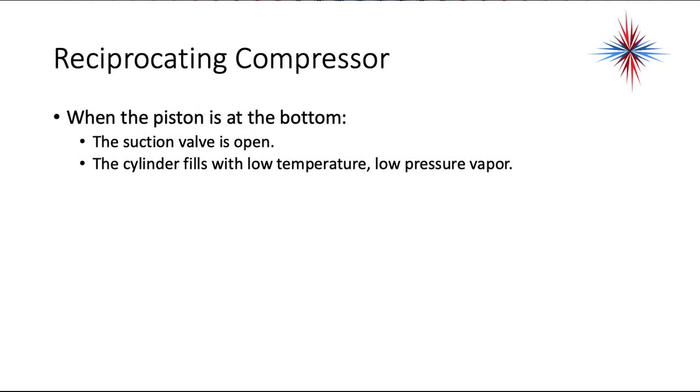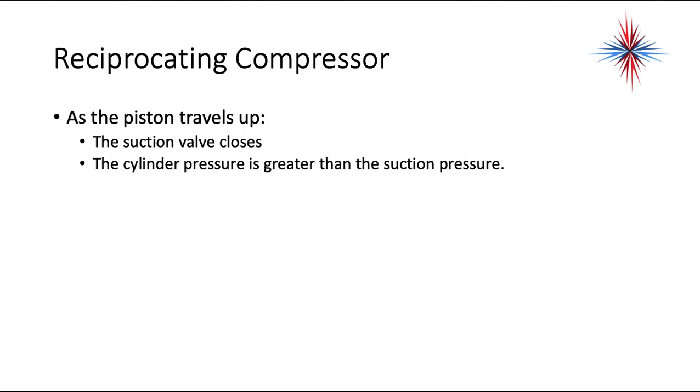When the piston is at the bottom, the suction valve is open. The cylinder fills with a low temperature, low pressure vapor. As the piston travels up, the suction valve closes. The cylinder pressure is greater than the suction pressure.